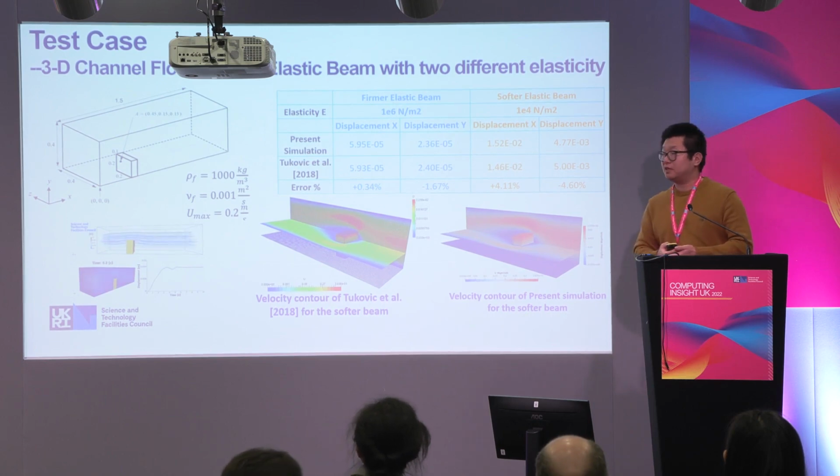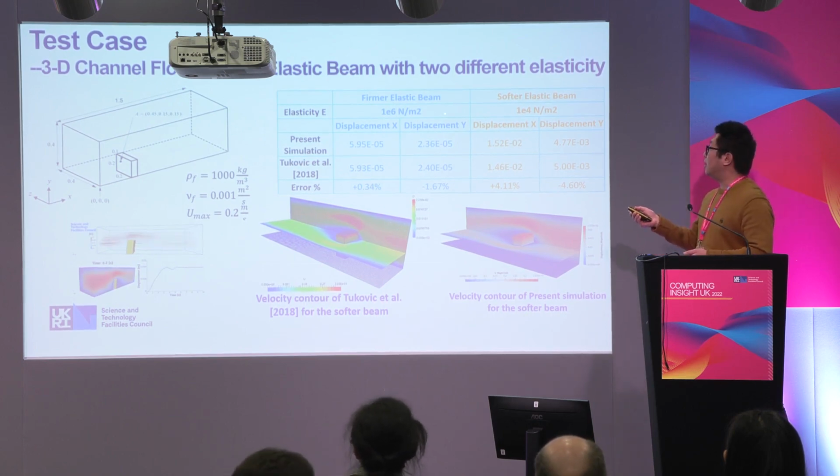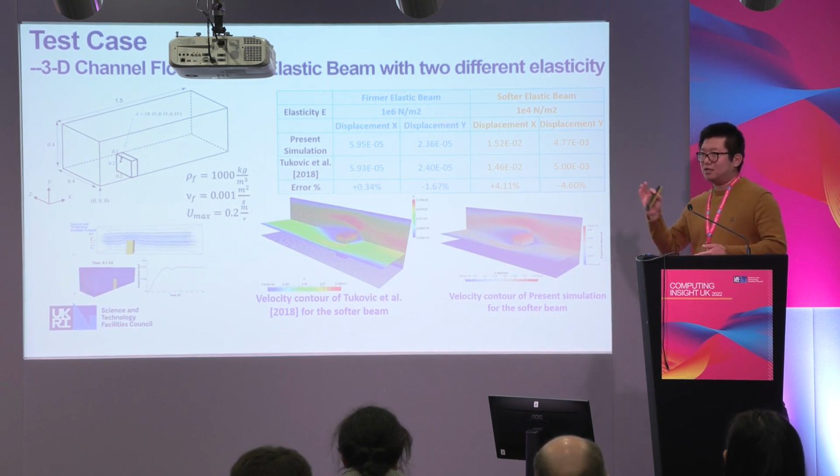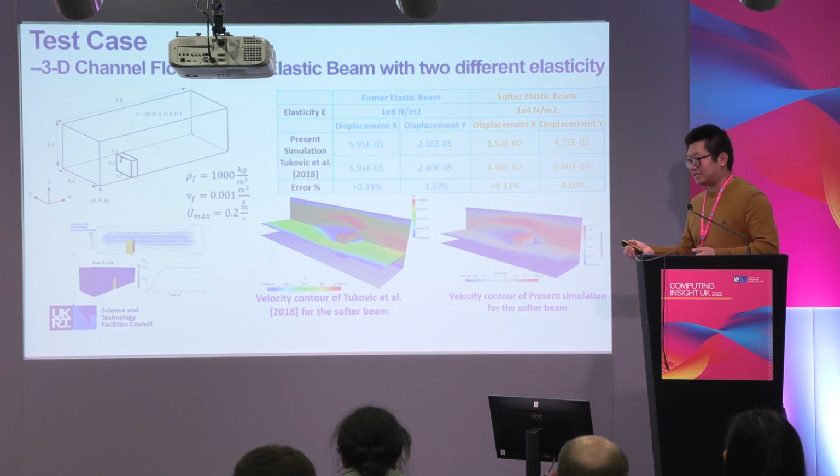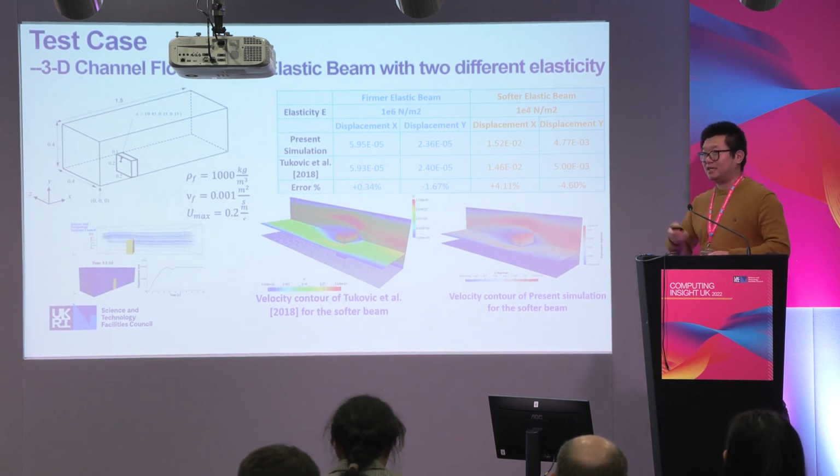And we also compared the quantitative values with the published data. There are two different cases that have been simulated. One with a firmer flexible beam. The other is a softer one, which involves the hyperelastic solver inside the structure solver. And both gave relatively good results.